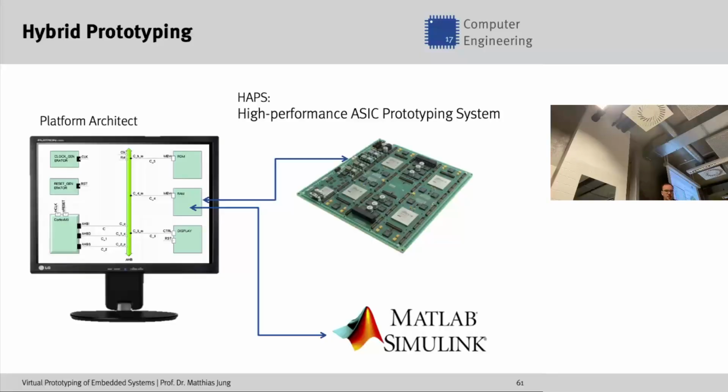So that makes a lot of sense. For example, if this is the model or the module that you are developing, or this IP block you are developing, and you want to test the RTL in a specific context. And the context is then basically simulated in software, and your RTL model is really synthesized on FPGA and is executed there as it would be executed on a real chip.